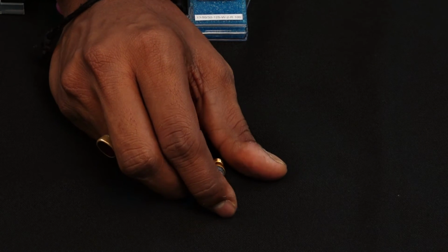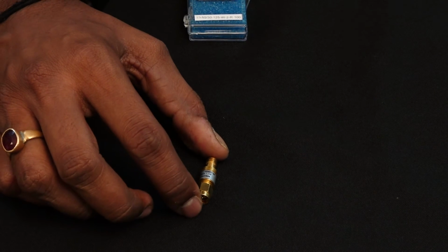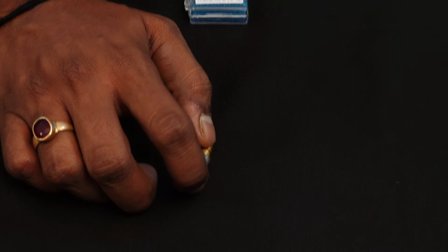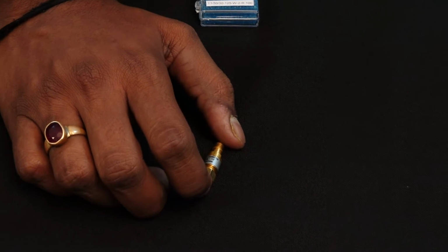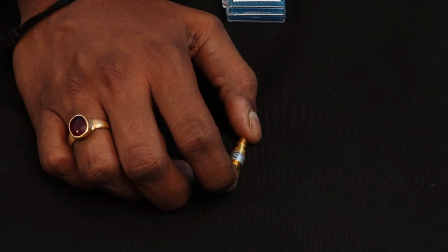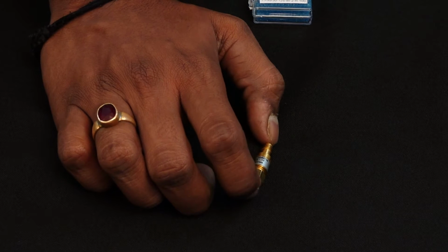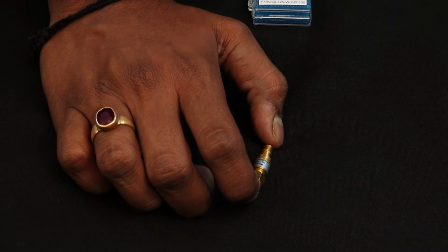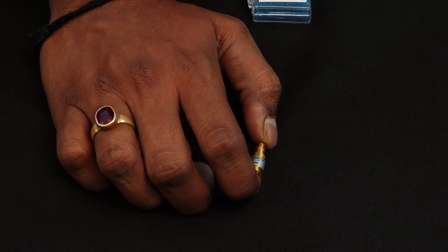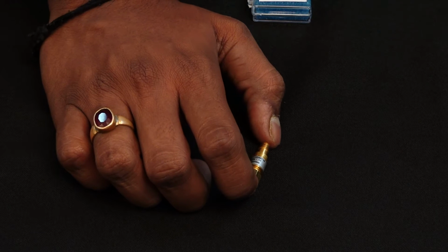These attenuators are high frequency attenuators that we use because they have to attenuate a very high frequency signal. They come in different specifications, and their specifications are not voltage to voltage, they are decibels. I'll talk about the ratings of different attenuators in the second video as well, and how these attenuators then impact the calibration setup that we use. Their purpose is to attenuate the signal coming at the oscilloscope to less than what the oscilloscope can actually handle. An oscilloscope can handle at its input only 5 volts of signal.